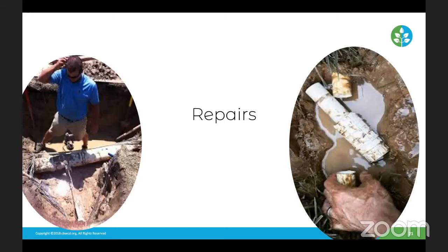I've seen them just snap in half, which means you would have to replace the valve. I've seen it where all it is is just a little O-ring that sits underneath it, where you can just go to any hardware store and get a little 10-cent rubber piece, screw it back in and it'll seal.